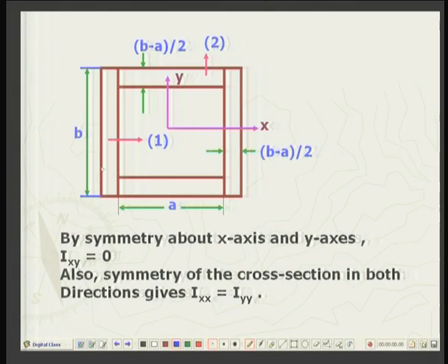So, this is simplified like this, that is, you have two vertical rectangles and two horizontal rectangles, and you can easily see that this rectangle is symmetrically placed to this rectangle and this rectangle is symmetrically placed to this rectangle. So, whatever the contribution of this rectangle about the middle axis will be the contribution of this, and similarly whatever the contribution to the second moments of this, same will be over here. So, I need to consider only one pair, the other pair will be just a repetition.